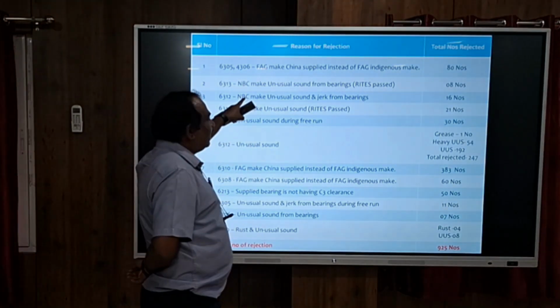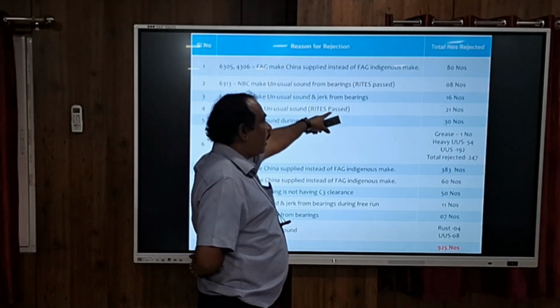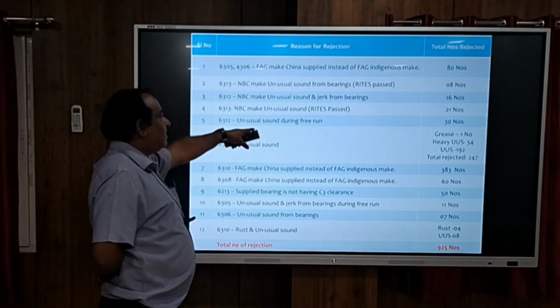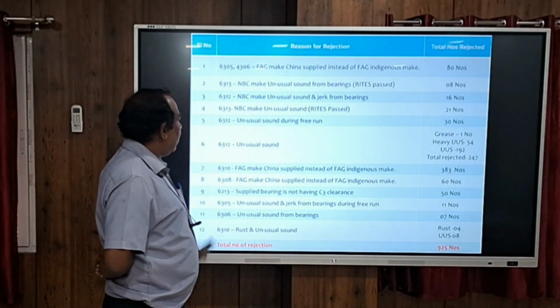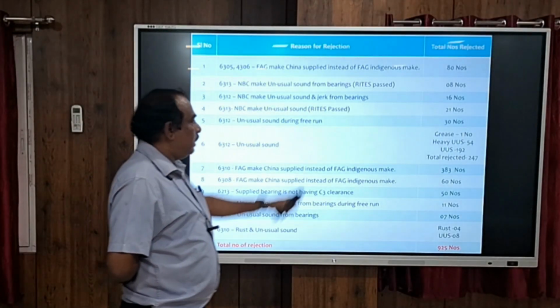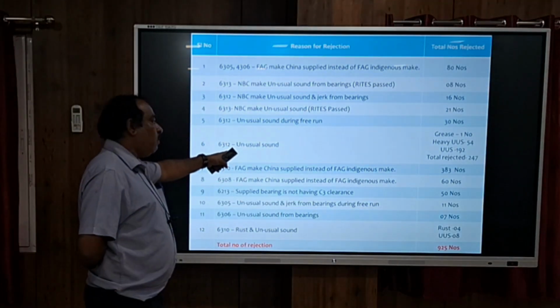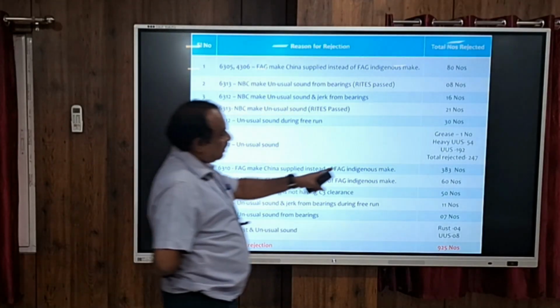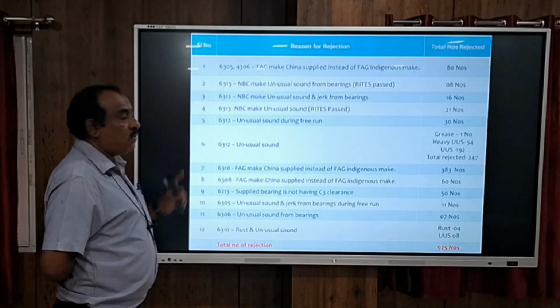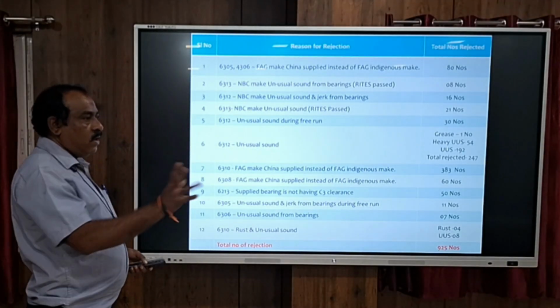Here, this NBC make, he has given with unusual sound. Even though test reports were passed, I rejected 8 bearings. And this NBC make, test reports passed were there, 21 numbers I have rejected. This 6312, during free rotation, there was sound in 30 numbers. And this 6312 SKF has supplied, I have rejected totally 247 numbers, sir, in this. He has lifted them and given also.